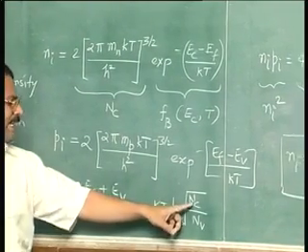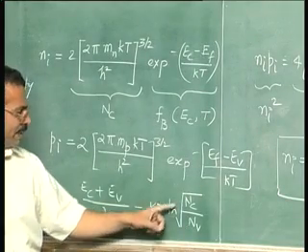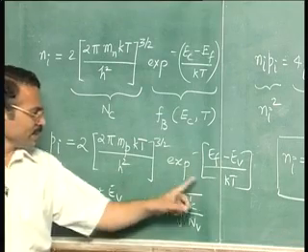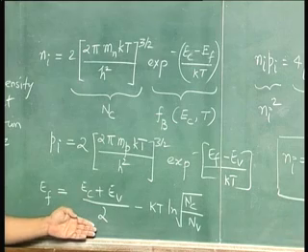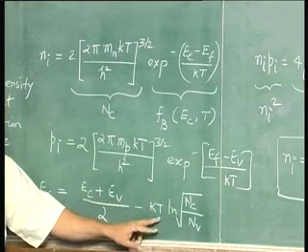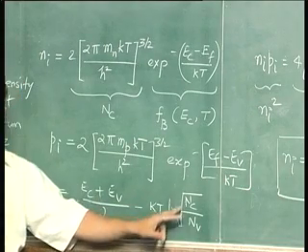So now you know that Nc and Nv are not very different, particularly if you are going to take the log of this quantity. Okay, this quantity is not going to be really significant. So it is almost EC plus EV by 2. And this term depends on temperature, but again this dependence on temperature is negligible because this quantity is small.